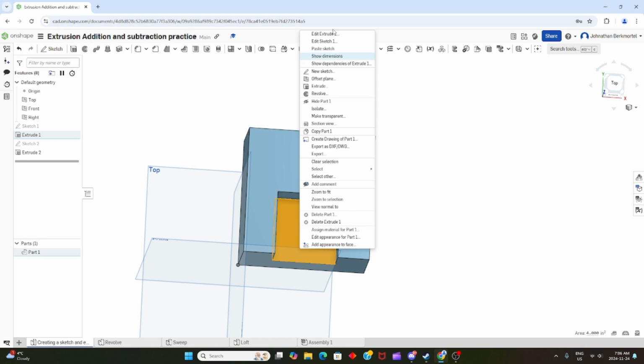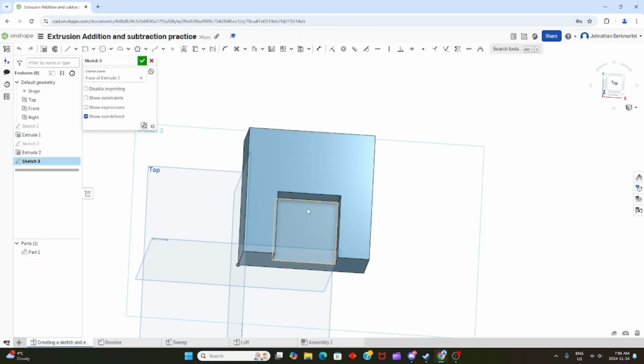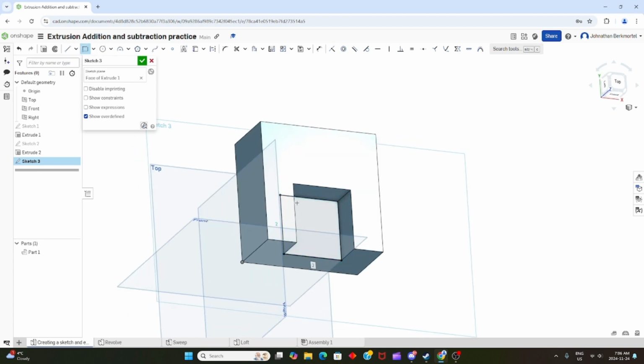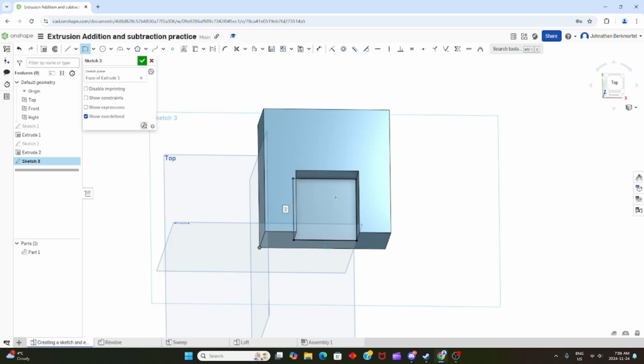So if we just select this face and create a new sketch, there's a couple options we can actually go about. We can create a rectangle and then just draw in this and use the corners and it automatically locks in geometry. Or we can use this tool, where is it? Use, project and convert, which means when we select that face and we hit that, it'll automatically outline it for us and follow its profile, which is what we'll use.